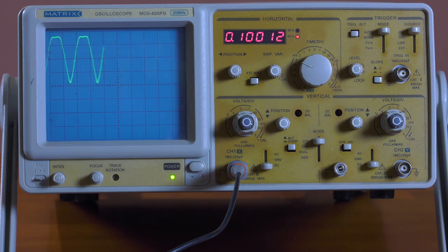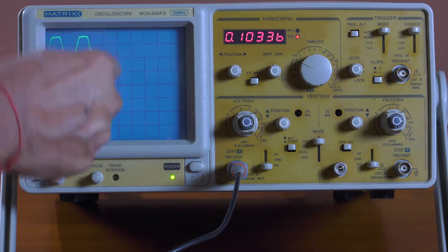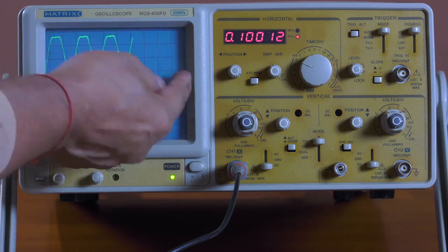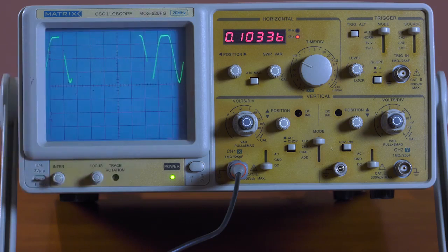If you want to get into a more efficient filter circuit, we'll use capacitors and inductors, but it's beyond the scope of this course. So we're just going to use a single capacitor to see how we can remove these peaks, if you like to call them, into a straight line graph, and that's what we are actually looking for. So that waveform is representing a full wave rectifier using 2 diodes and a center tap transformer.